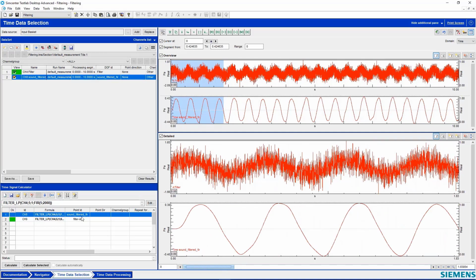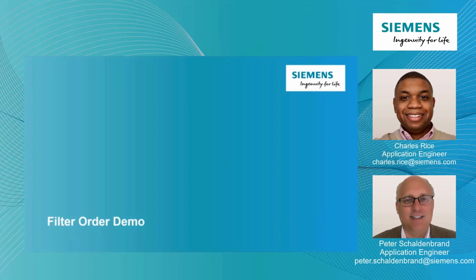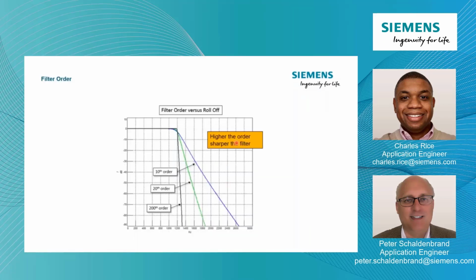So that is an example of filter order, Charles. Is that kind of what you were hoping to see? That's exactly what I was hoping to see, Pete. Thanks a lot. So I have another slide here, just basically summing up what Pete was talking about there. When it comes to defining these FIR filters, the higher the order, the sharper the filter. And we can see that from 10 to 200, we can see quite a bit of difference.